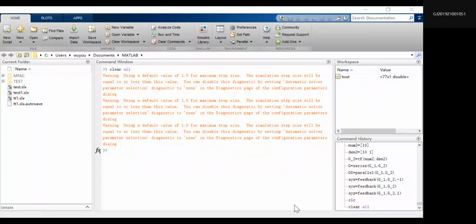500, and why is it actually like 700? Overshoot. Of course, it has overshoot, several overshoots, and the biggest one happened here. So this is an oscillation system. Though it has overshoot first, as time tends to infinity we can imagine it will be stable at maybe 500, or bigger or less than 500, but the accuracy is not that precise.